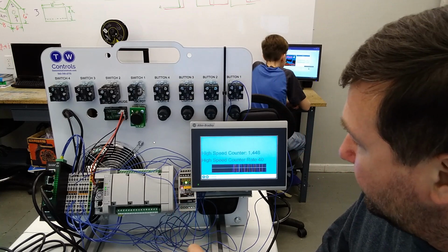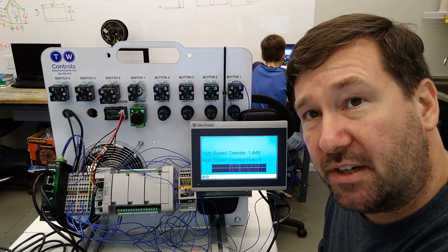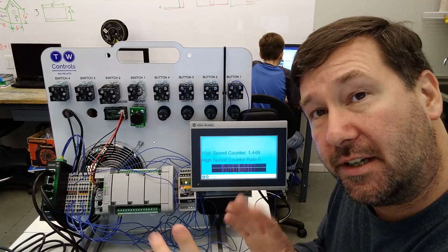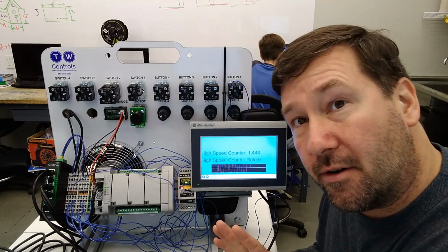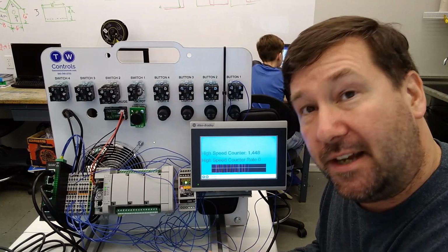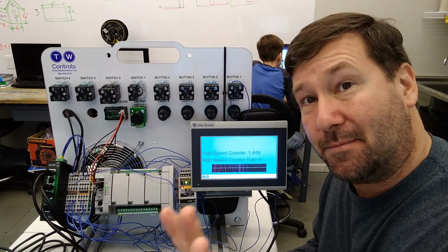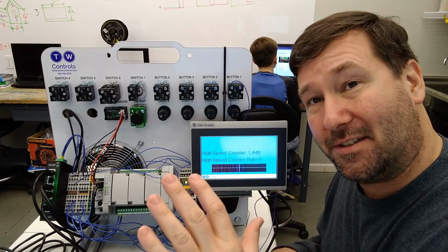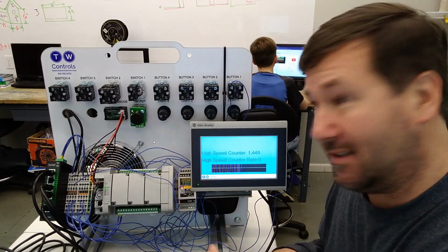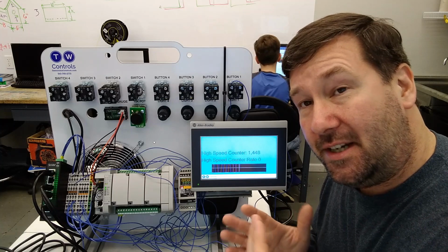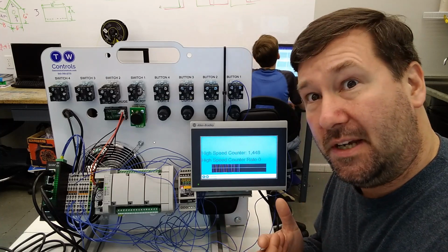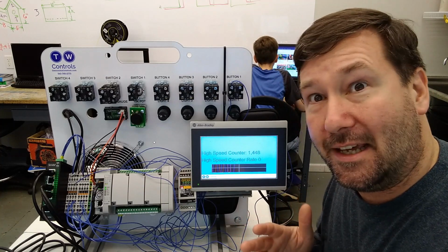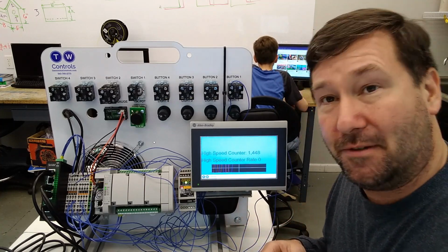We'll click that, and our rate went to 0. So what happened there? We were at 10 Hertz, looking good. We go to 100 Hertz, and everything flops down. And guys, you'd be surprised at the times that I've actually, well, one, that I've done this, but also that I've gotten calls about this. They're like, hey, we got a new machine and it runs great at slow speeds, but the more we speed it up, the worse it runs, which could mean a lot of things, but a lot of times it is these input filters.